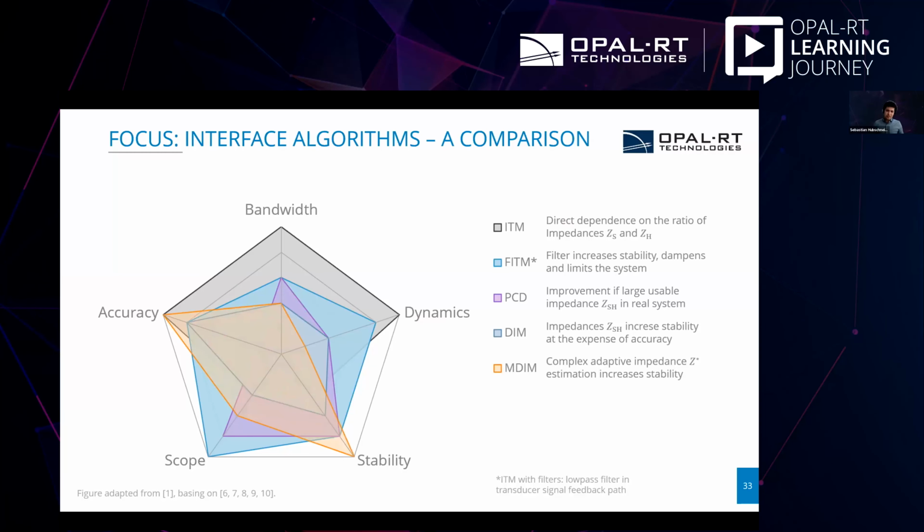An upgrade of this damping impedance method would be the modified damping impedance method, where we upgrade it by adjusting the damping impedance utilized. The performance of the algorithm then is strongly dependent on the algorithm adjusting the guessed impedance, or the impedance of the device under test.